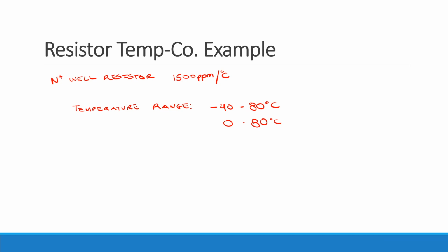For industry kinds of things, you probably do need to go below 0, because you might happen to build, I don't know, a Wii that's going to be played in Alaska or something like that. So you usually go to maybe minus 10 or so, but 0 up to about 80 degrees also makes some sense. If you really push, you'll maybe go up to 100 C, but not much beyond that, because things start getting soft and squishy in the chip when you do that. So let's make our life easy and say it was 0 to 100 degrees C.